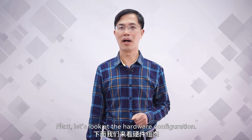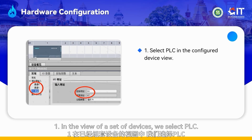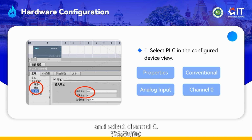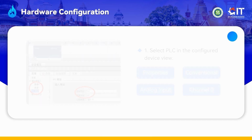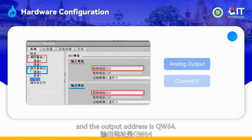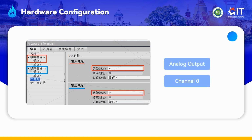Next, let's look at the hardware configuration. 1. In the view of a set of devices, we select PLC. Then, we realize regular analog quantity input and select channel 0. The address is IW64. Channel 0 is selected for analog quantity output and the output address is QW64.